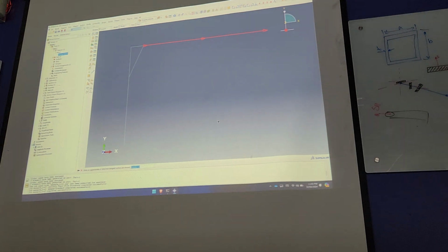It is 0 in y, 0 in x, and minus 1 in z. That's your vector. So basically what you're instructing Abaqus is saying, I want my 1 to point in this direction.